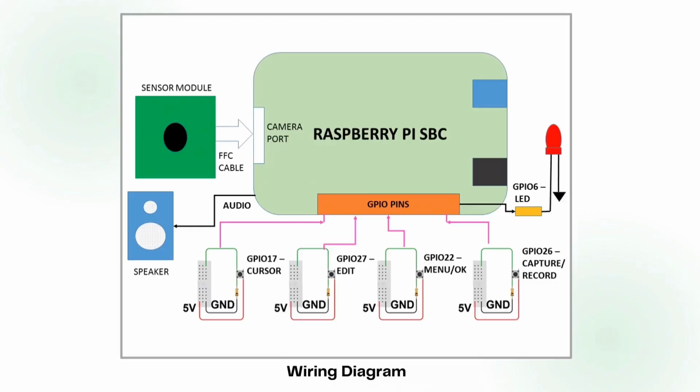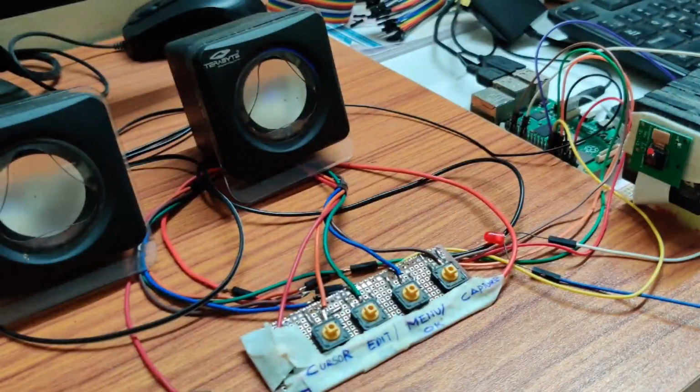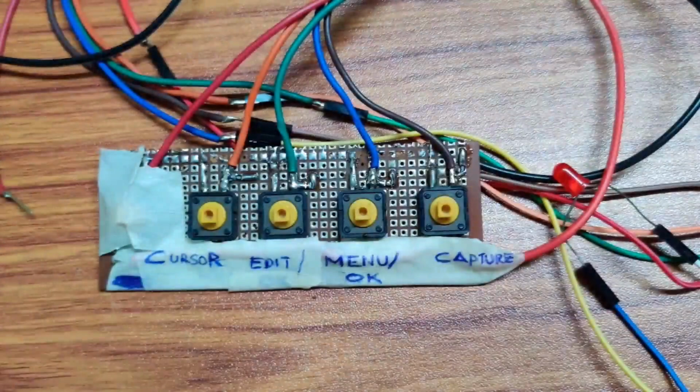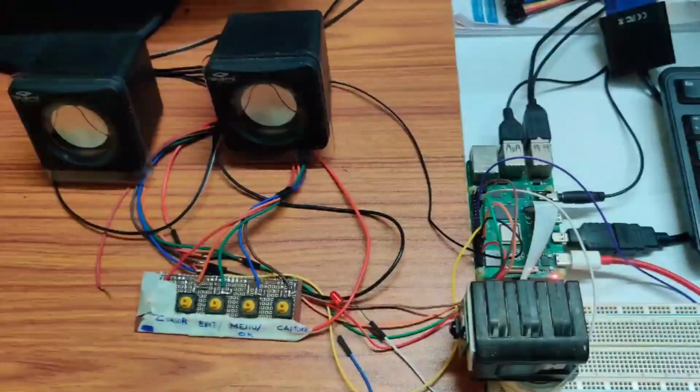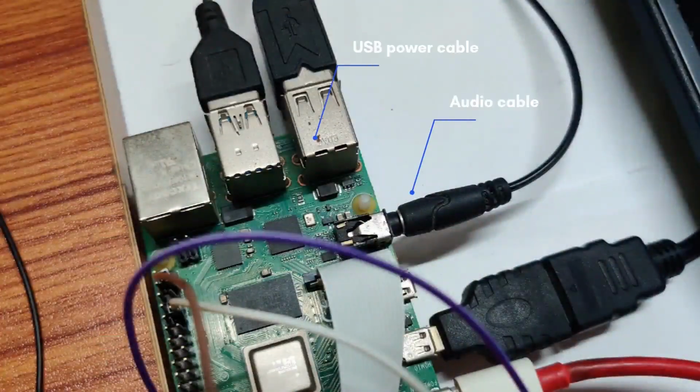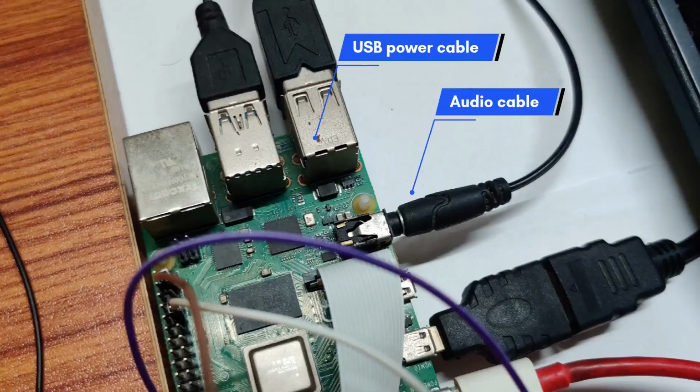You can see the actual setup here. I have soldered the push buttons to a Vero board for easily wiring it to the Raspberry Pi using hookup wires. I am using a USB-powered speaker. The USB cable for powering the speaker is connected to the USB connector of Raspberry Pi. The audio stereo cable from the speaker is connected to the audio output of the Raspberry Pi SBC.